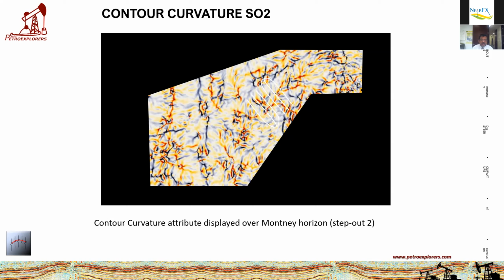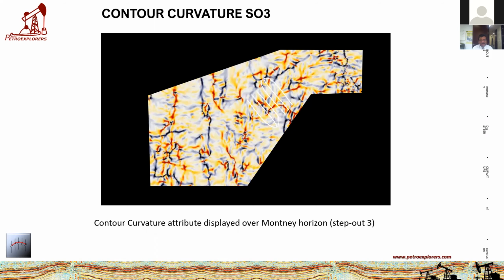wells were. When they were drilling the new wells, they had tracers on the older wells, and so they would start getting the frac fluids showing up, or pressure change within the existing tracers. So showing that there is communication from well to well on certain ones. And we were quite surprised because it was a new kind of finding. And since then they have used the same contour curvature many times, because what it is, it's really